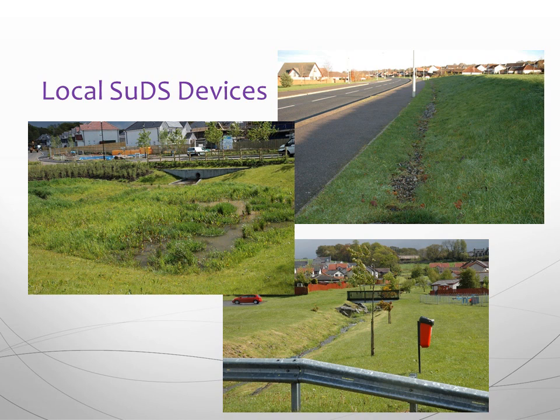These are some typical urban SuDS devices in operation. The first image on the left appears to be a retention basin or possibly a wet detention basin, as it appears to have a wet area. The surface water runoff from the housing estate in the background is transported through a conventional piping system into the basin. After attenuation and treatment, the surface water is discharged into a small stream.